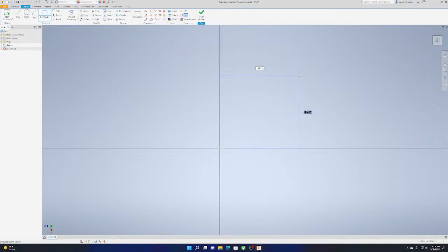But let's make a little cube. There are two ways you can do this. You can eyeball it, moving your hand to get to 1 inch. You can do it, it's just not recommended. What I do is type in the values. You can see that the value on the right, the vertical, is highlighted in dark blue, and we can just start typing.